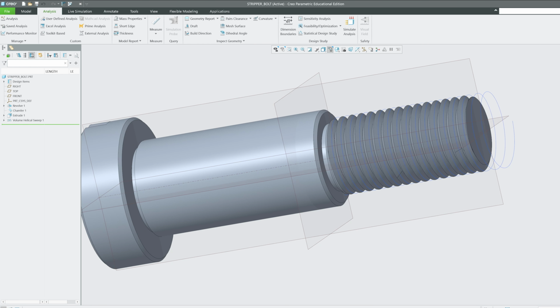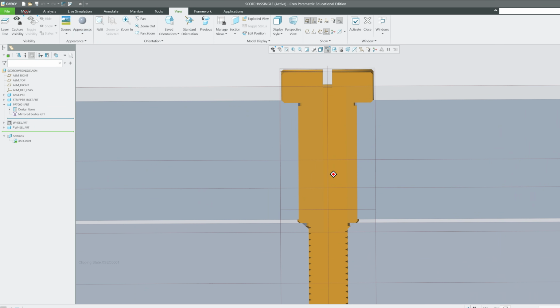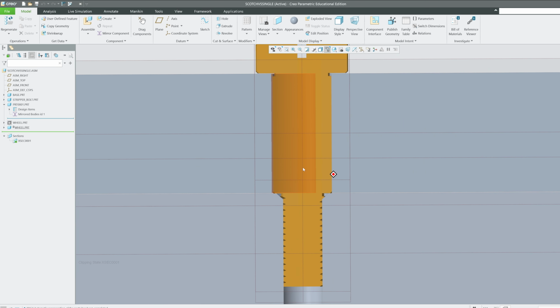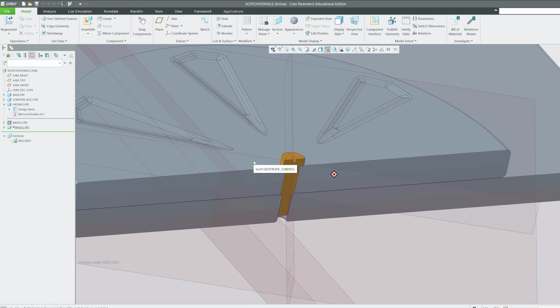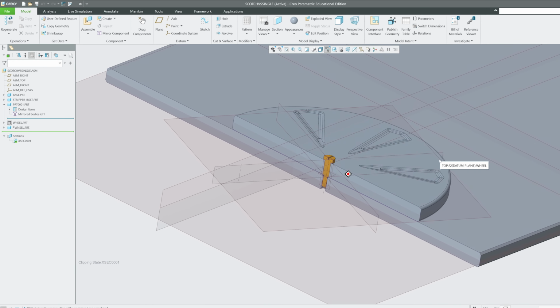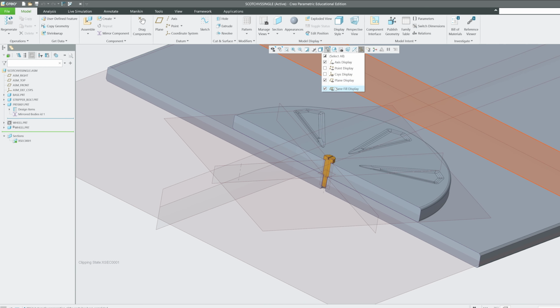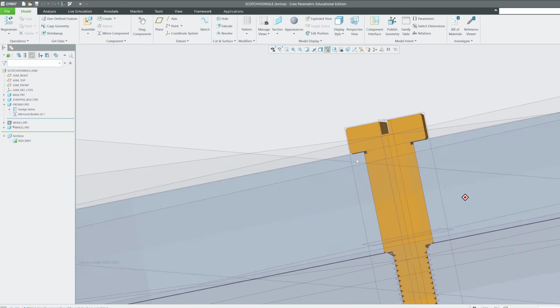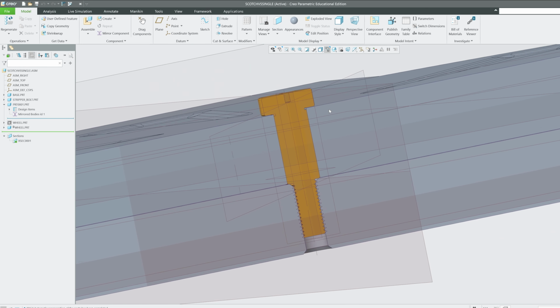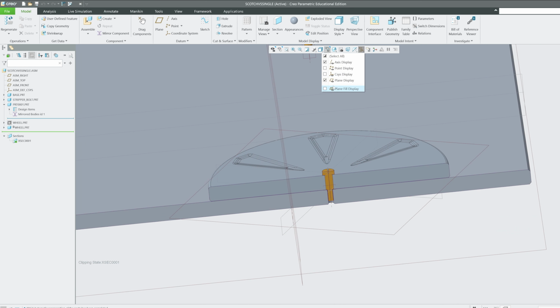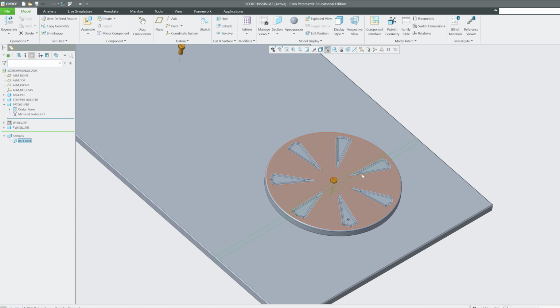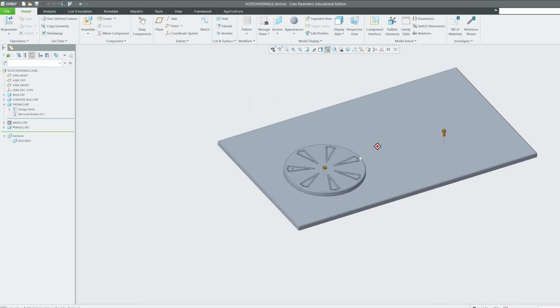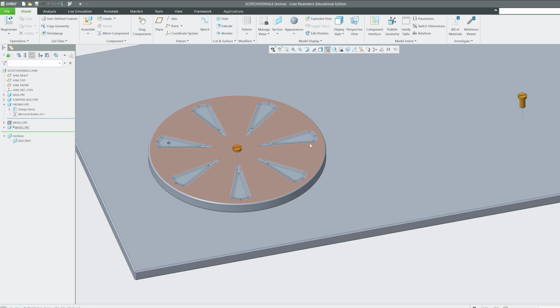Yep. Let's close this. And now if I refresh, you're going to see both sides the clearance is 0.1. So that's why I made this wheel 19.8, and this stripper bolt has a gap of 20. So 0.2 is a clearance that I kept so that the wheel can rotate freely. Of course, the flatness of this wheel needs to be awesome, and of course it will be, because I'm just thinking of this wheel to be milled or machined instead of injection molded or something else.